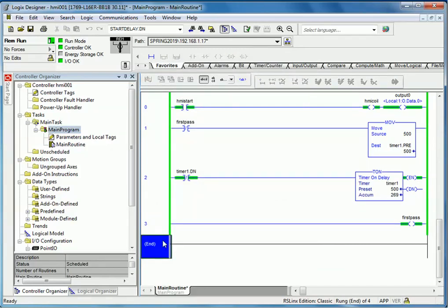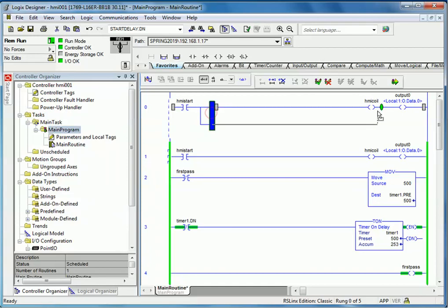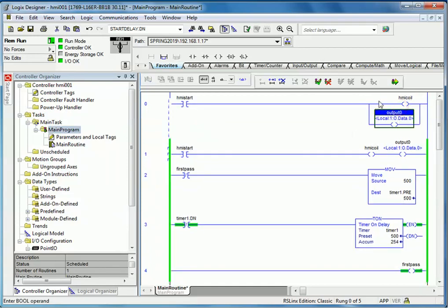Button. So you can see that it works. You know, in real life, if we were wiring up relay coils, this would not work. But this is logic. So you can do that if you like it. I personally don't like that. I like to see them in parallel because that's more like actual motor controls.